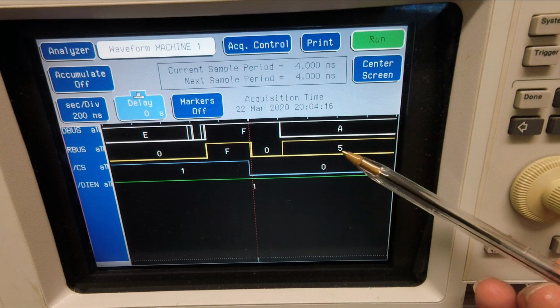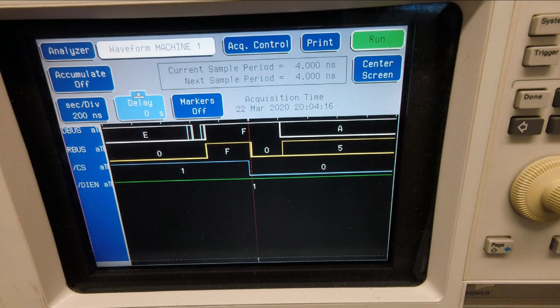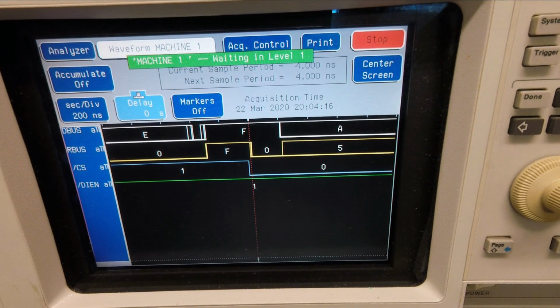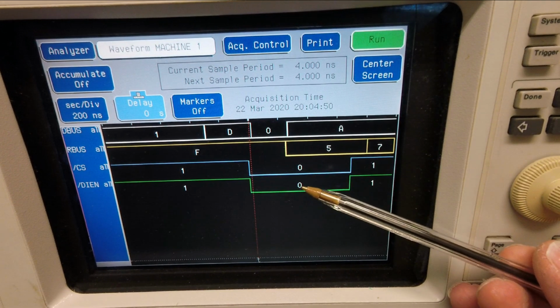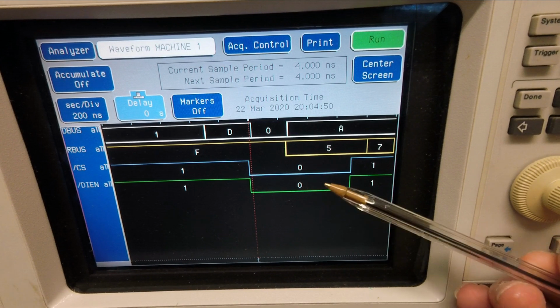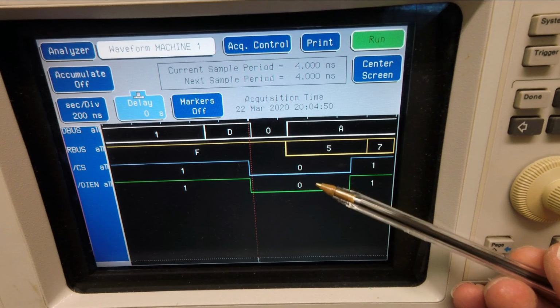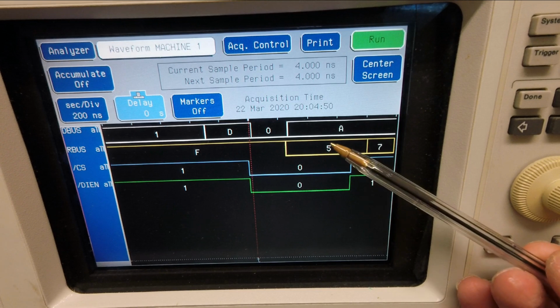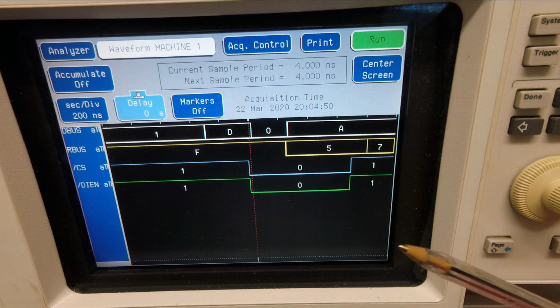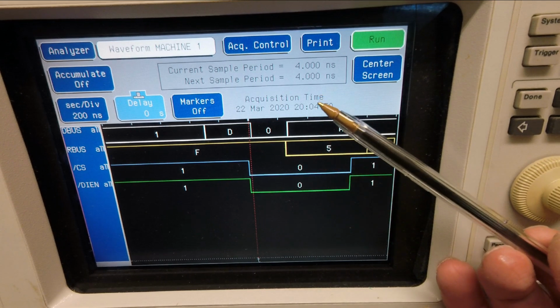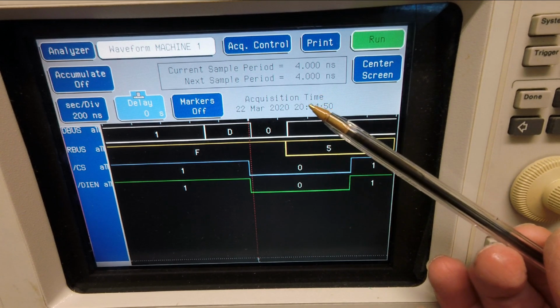I'll do the reverse, that's doing a read, so I'll do display 8000, 9000, rearm, turn. Right, there we go. Data direction has changed state onto a 0, so we're actually reading out of the RAM now. We're getting 5 from the RAM bus side, and that's being inverted back to an A on the data bus side. So it looks like the setup of the analyzer is correct.